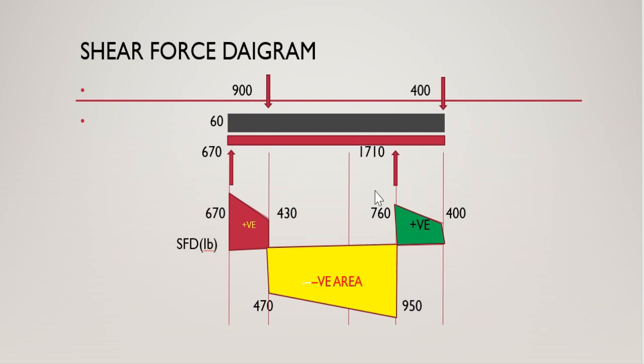So when we solve these two values, we got the value of 740, that goes upward, because this is the point load. For a point load, we have to go straight. For a distributed load, we have to draw a line that is inclined over the entire length. So again we have a distributed load. Due to this distributed load that acts downward, we got the value of 400. Again, this is 400, this is a positive value, and this is a negative value. So when we sum these two values, we got the value of 0 shear force at point D.